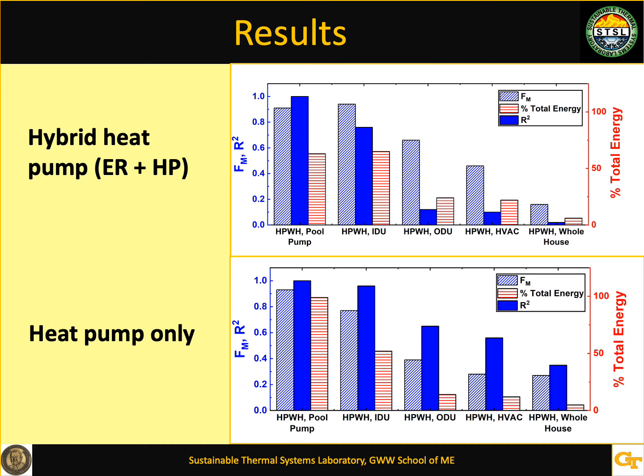The R-squared statistic, as mentioned previously, is the coefficient of determination calculated between the change in power draw of the appliance signal and the main signal. So it's a predictive metric in this case and not a measure of the NILM accuracy. We see that when the change in the appliance power is more closely correlated with the change in the mains power, as shown by R-squared, the disaggregation, as measured by the F-score, is more accurate.